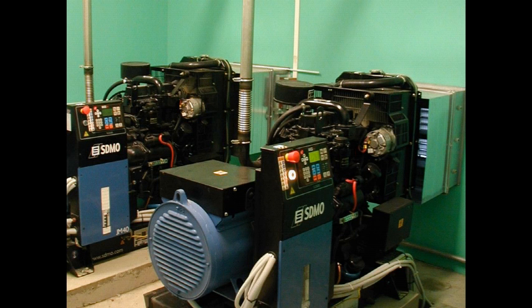This is an example of two diesel gensets, or generator sets to use the long name, each rated about 40 kilowatts. At half load, such a genset consumes 6 liters of fuel per hour. With Swedish fuel prices, it means that only the fuel cost corresponds to about €0.5 per kilowatt hour electricity generated. If you count the total costs, it's even more expensive. €1 per kilowatt hour is not unusual on remote locations.